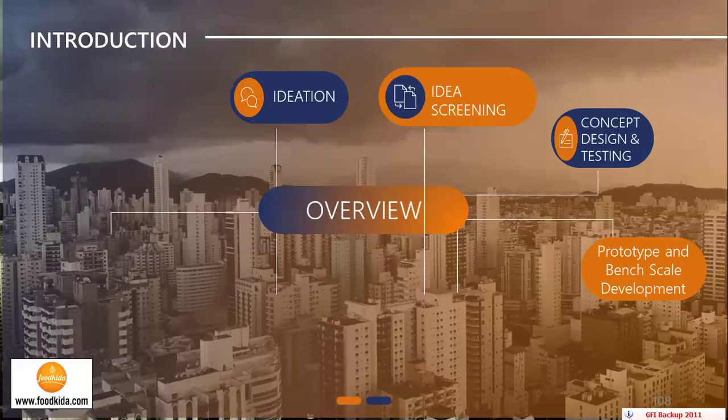So, for example, PET is transparent. Broadly, PET is used most of the times. PET is reverse printed. Poly is used as an inside layer for sealing because it is heat sealable, and all those things. Where MET is used and why MET is used. Basic structures of packaging, primary packaging, and then the secondary packaging, the carton, how we select the carton, how you decide a compression strength for that carton. What are the bases used for deciding the compression strength, CS, for the carton? Hope you people are aware of the terminologies which I am using right now.